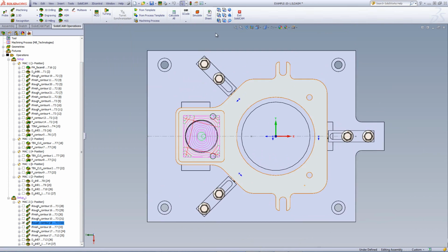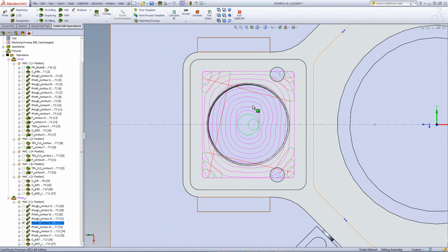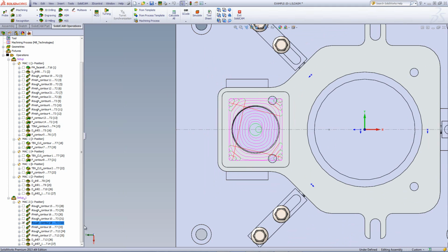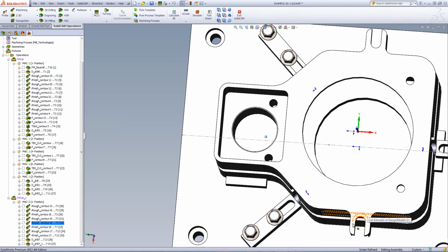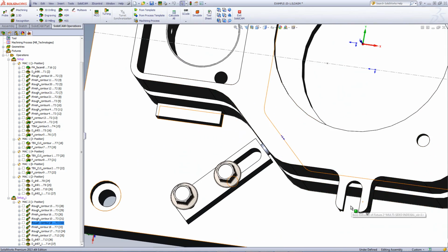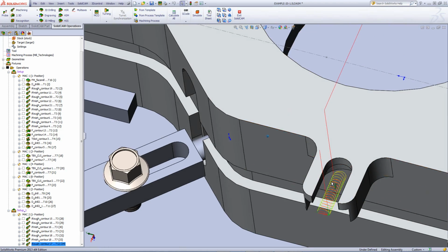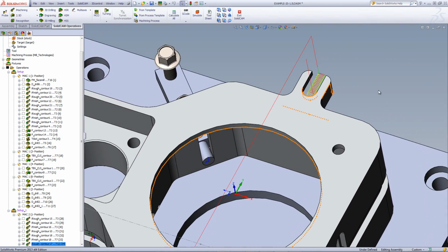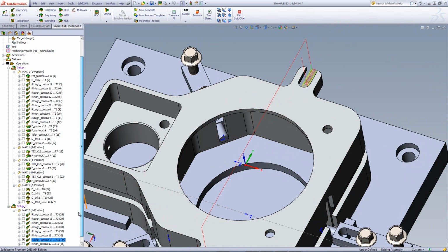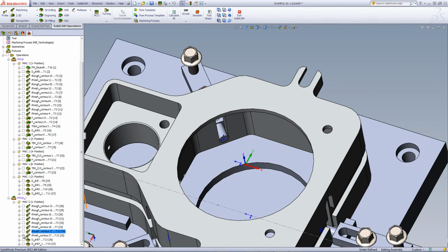Taking a look at the tool path from the top view, you can see that it has the morphed spiral tool path as well as trapezoidal for the corners itself. Now, in addition to this iMachining operation that I needed for this pocket over here, we also still have these areas over here that I did not mill out yet. So for that, I've also used the option of iMachining, creating for this slot over here as well as for the slot on the other side, doing both a rough and finish operation for those slots as well.